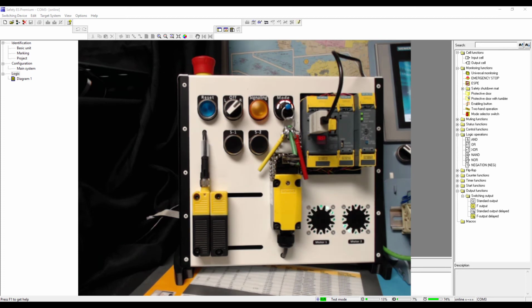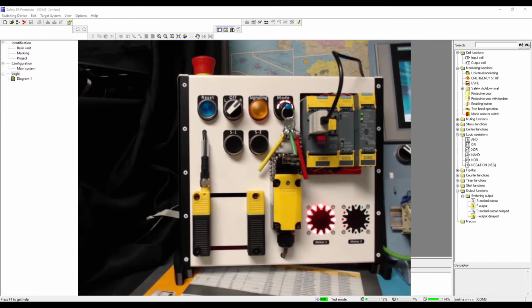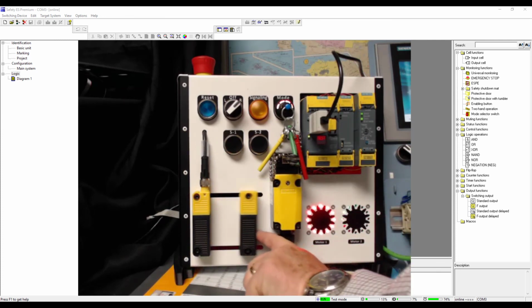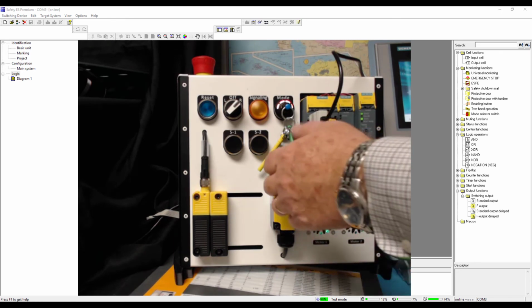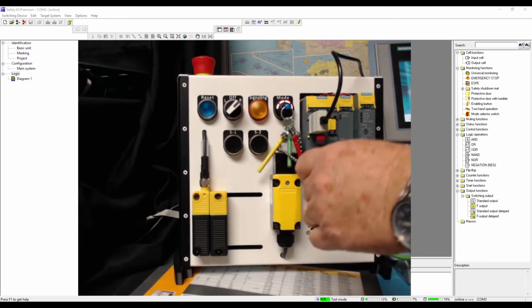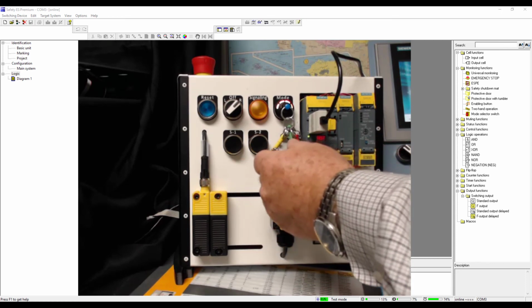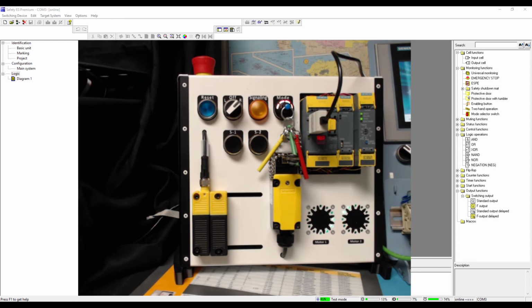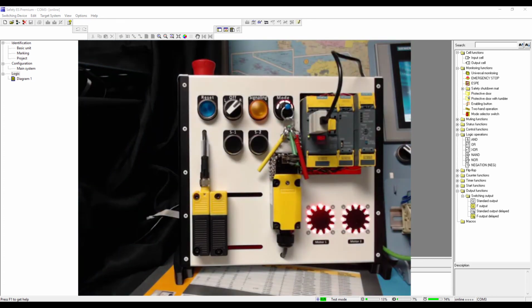And again, if you open up the RFID switch, it'll stop motor 1 and have the automatic reset. And if I pull the interlock out, I stop motor number 2. But it starts back up automatically. And if I hit the e-stop, it now shuts off both outputs in an area e-stop function.